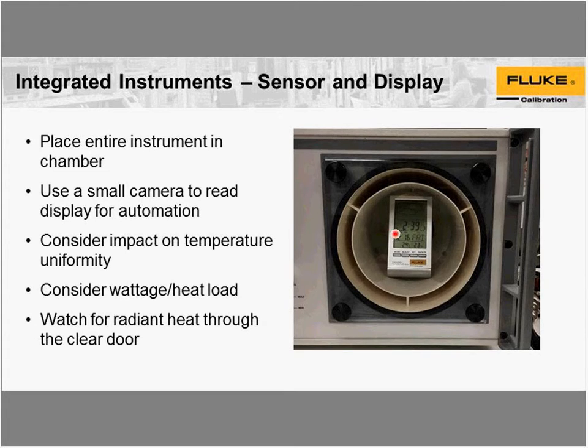Laboratories will use a small camera inside the chamber to read the display through OCR, which is an interesting technique. But also consider that if these things are fairly big, they may impair airflow inside the chamber and can cause temperature gradients.